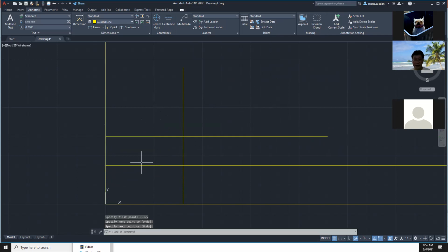So we create another line. The depth is 3, right? So to be easier, I move coordinate to here first, and then I create another line. 3. So we start from 3. Line 0 and 3, and then we extend it out. All right. So the top is here.